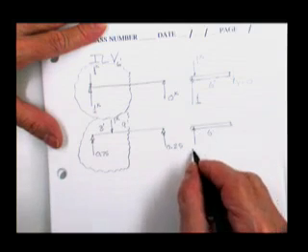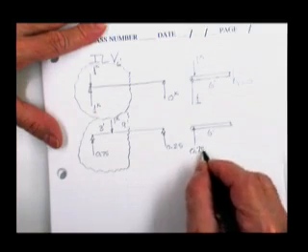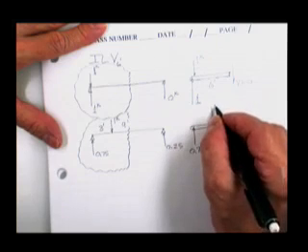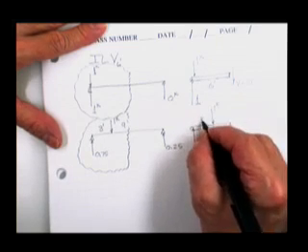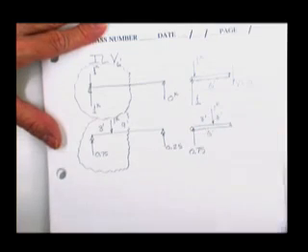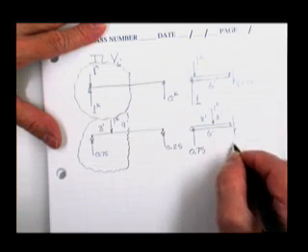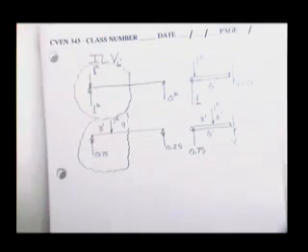The reaction on the left end is 0.75, and the load at the 3-foot mark is 1. There's my shear. Incidentally, I'm going to use positive shears. I'm just going to stick them on there positive. If they come out minus, I'll plot them below the line.